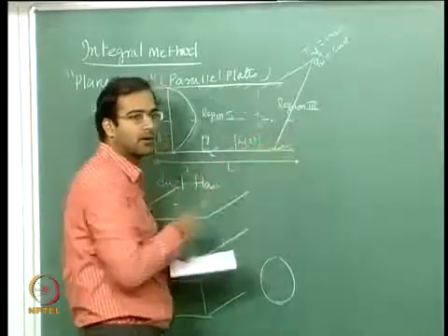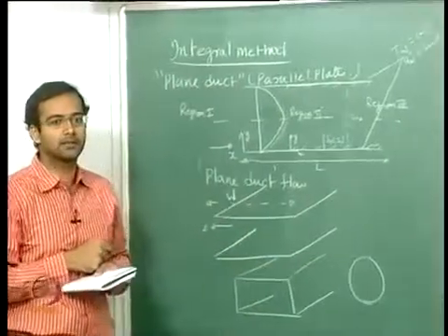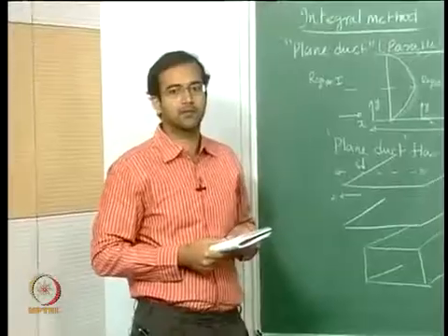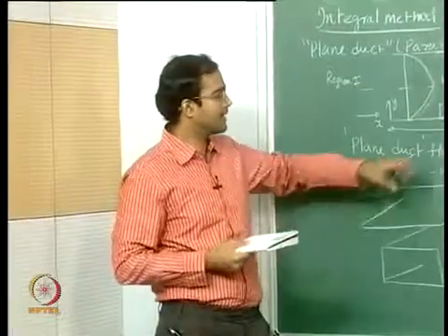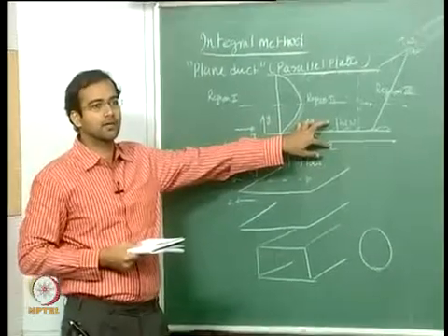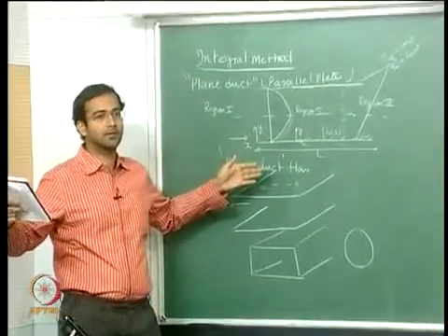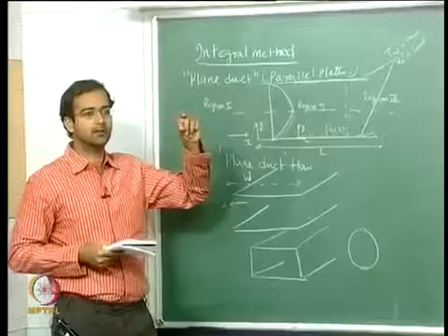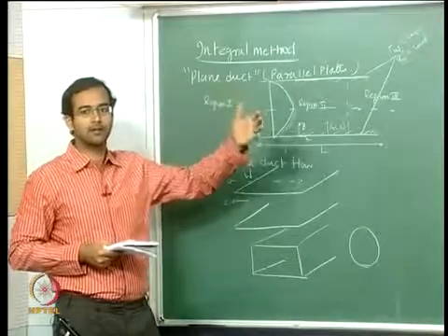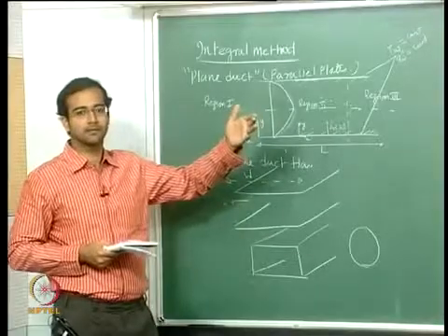and definitely your boundary layer equations are not valid once they fully merge, because there are no boundary layers, everywhere it is dominated by viscous effects. So a boundary layer, as the definition goes, is a region which, if you look at the total length of the plate compared to that, is very small, so your delta by L has to be very small, and away from the boundary layer the flow has to be inviscid.